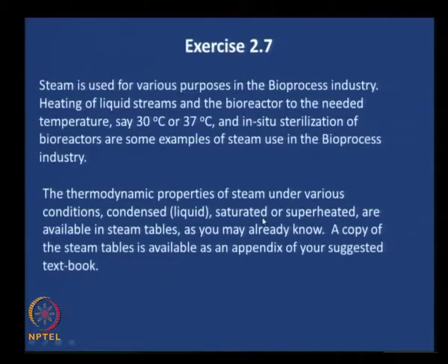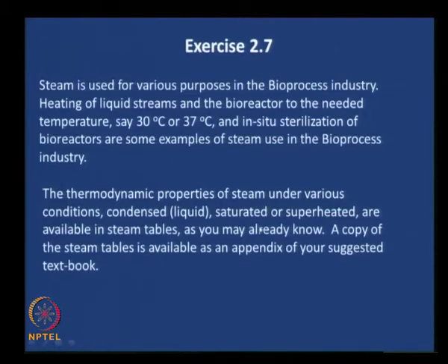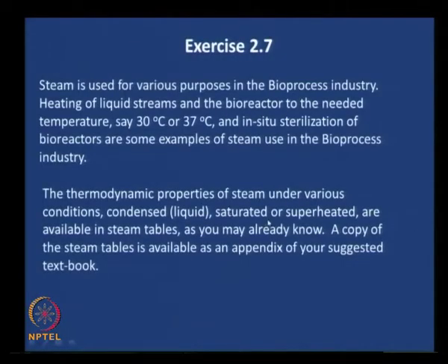What does saturated mean? Recall the phase diagrams that we reviewed in the first module. We had a PT diagram, pressure versus temperature diagram, and there we had the fusion line, the vaporization line. Let us focus on the vaporization line. The points on the vaporization line correspond to saturated conditions, and if steam is in that state, it is called saturated steam. Or if you look at a PV diagram, pressure versus specific volume, we had a dome, and the conditions inside the dome correspond to the saturated conditions. And superheated, of course, we know it is completely a vapor. Therefore, these two are the ones that are usually of interest to us.